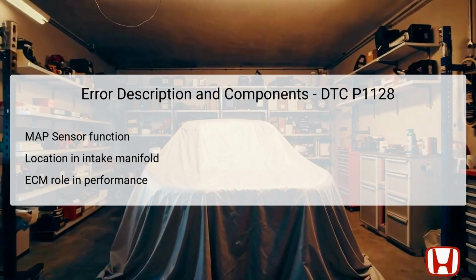When the engine is under various loads and speeds, the MAP sensor provides the ECM with real-time pressure data, which is essential for optimal fuel injection. Incorrect readings can lead to poor fuel economy, decreased performance, or engine stalling. Therefore, proper diagnosis is crucial to ensure that the MAP sensor is functioning correctly before replacing it.